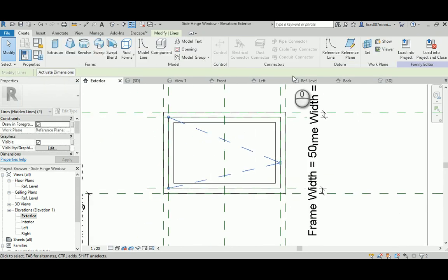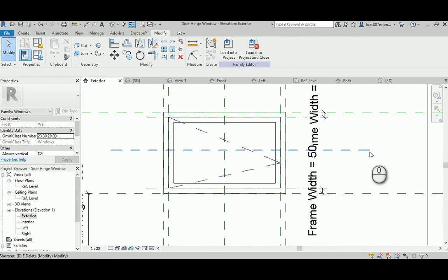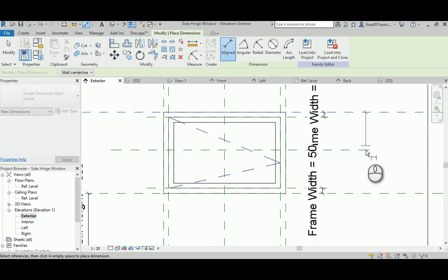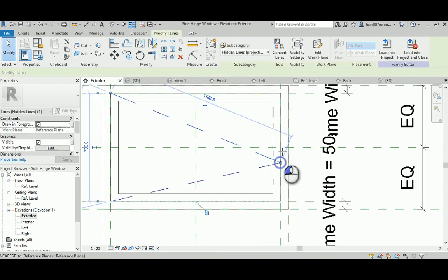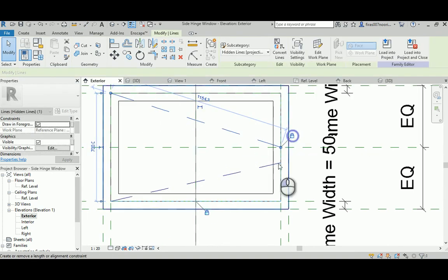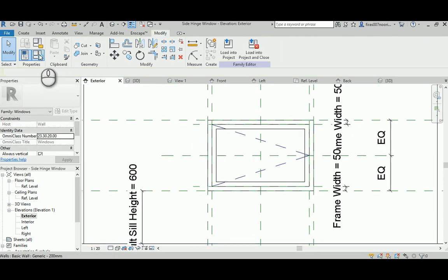So to fix this, I'm gonna create a reference plane quickly. Careful with this dude, don't over-constrain it. It's already been defined now. Move this guy here, lock, and I'm gonna then move this guy here. It's already locked, so now it should work.